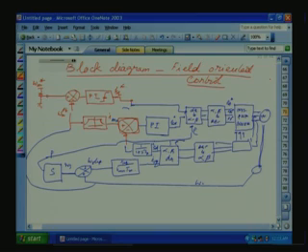See, in this field oriented control, we have used the current hysteresis controller. That means here we generate the ISQ and ISD reference, then using rho we convert it into I alpha, I beta, then alpha beta to ABC. Then for the ABC current and the ABC feedback, we will use the simple hysteresis controller.